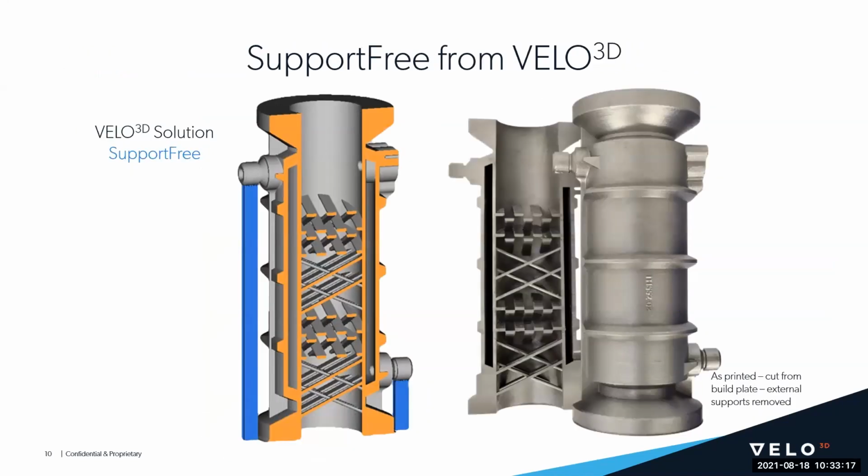So fortunately, with our system, we were able to avoid a lot of the headaches with supports. The baffles can be printed at their current angle without any issue. None of the internal geometry needed support. And then only minor modifications were made to the exterior of the part, and I'll go into those in a little bit.